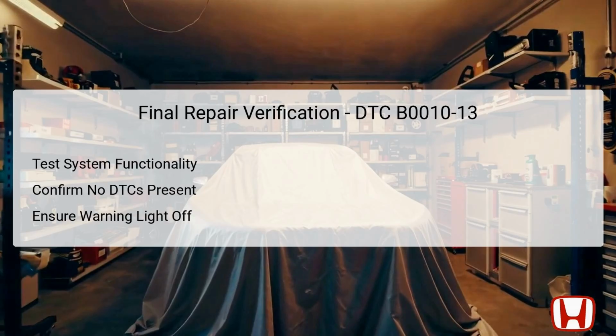After the repairs are completed, the final verification is critical. Begin by testing the entire SRS system to confirm its functionality. This includes checking the airbag deployment and ensuring all components operate as designed. It's vital to verify that no diagnostic trouble codes, DTCs, are present.